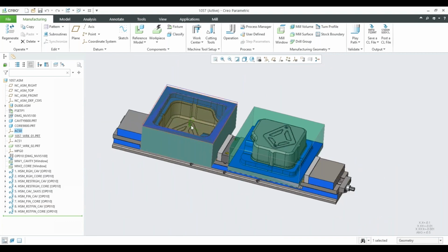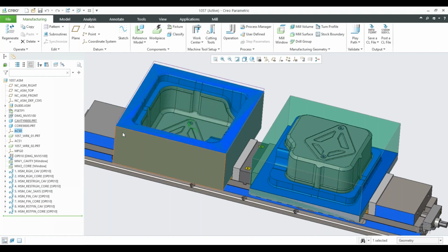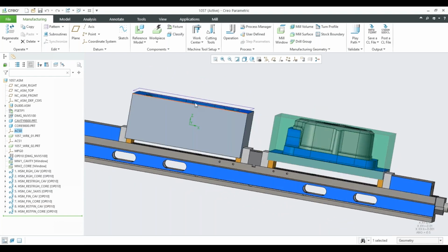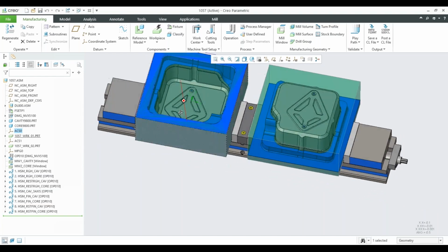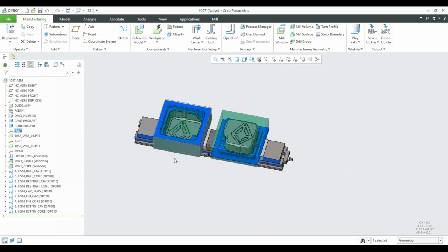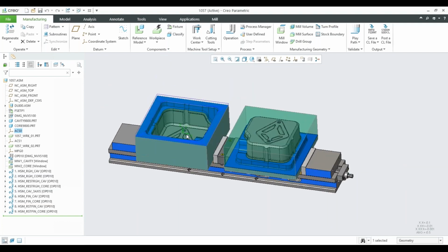And if you're planning your setup, there are many options. I could have used the corner here if I wanted to calculate my tool path from there. I could have used the top surface over here, and then maybe the center of my part. A lot of guys like to pick up their workpieces on the machines like that as well. That's an easy one to do as well. Corners are also very popular, but then you need to check that your parts are straight on your machine. So always know where your path is going to be calculated from, and that coordinate system is very important.